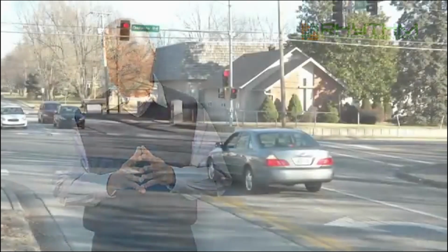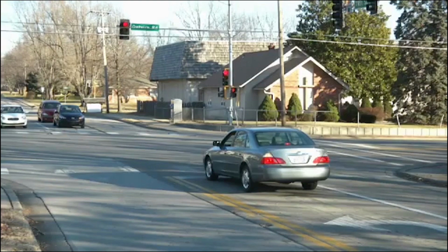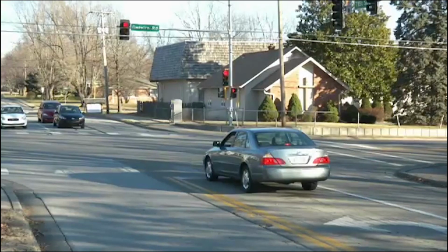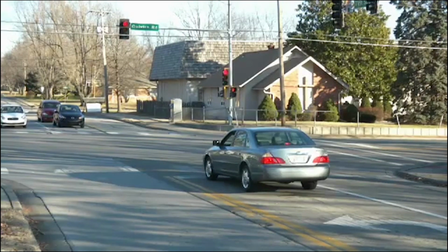Since that time, when I was working with the city of Springfield, till now, all I've done is optimize synchronized traffic signals. The number one phone call I used to get when I was in the public sector was this: why am I waiting on the side street when there is nobody on the main street? And I will try to explain. It's because there is a hold on the main street once the side streets are gapped out.